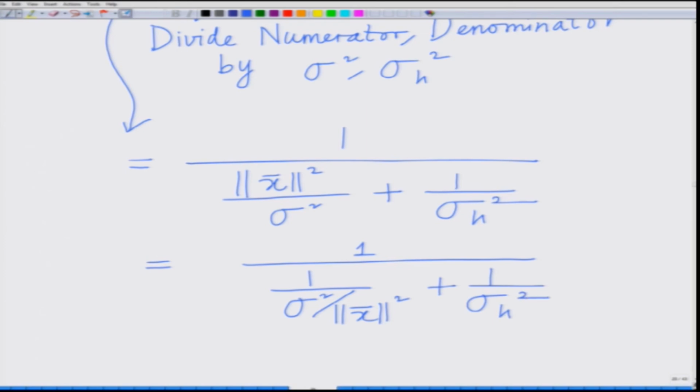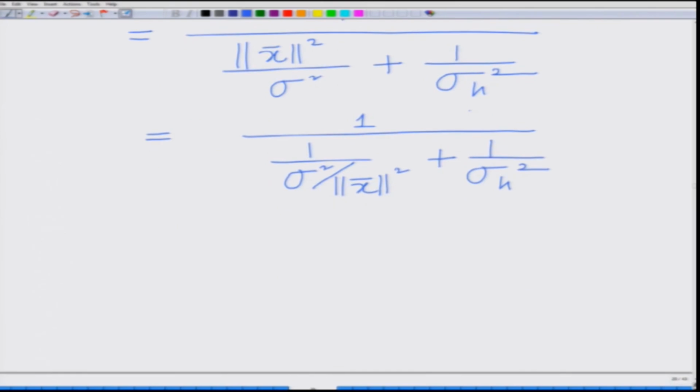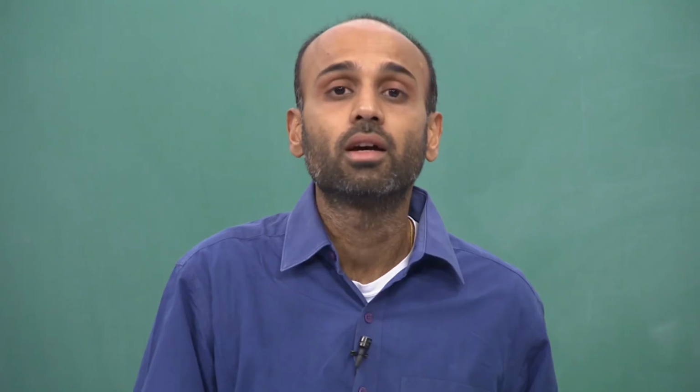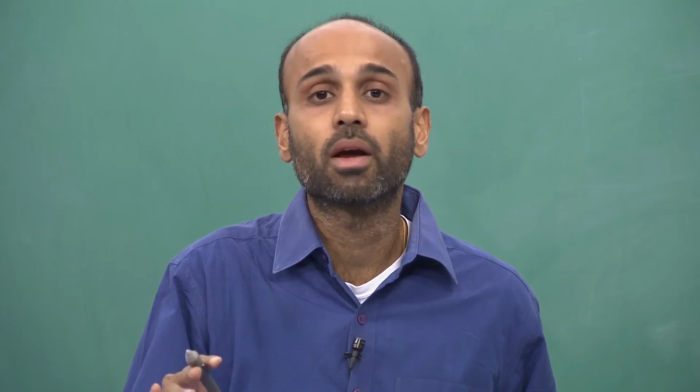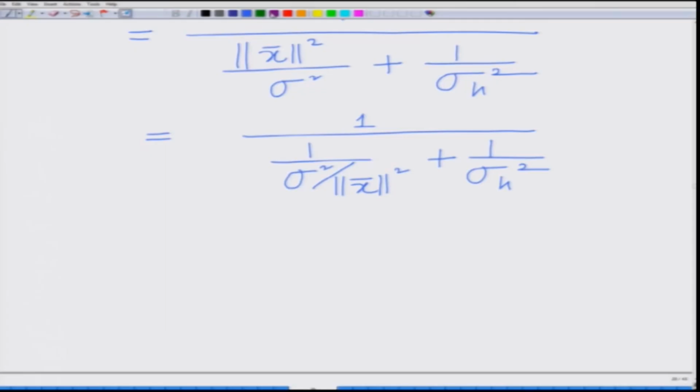Okay. And now realize that this expression is also valid for the case where the channel coefficient h is complex. Alright, all you have to do is substitute norm x bar square by magnitude x1 square plus magnitude x2 square, so on up to magnitude xn square. Alright, we already said that. Okay. Now observe, so let me make a note of that. This is also valid for the complex coefficient h. This is also the MMSE for the estimation of a complex channel coefficient h, so also valid for a complex channel coefficient.